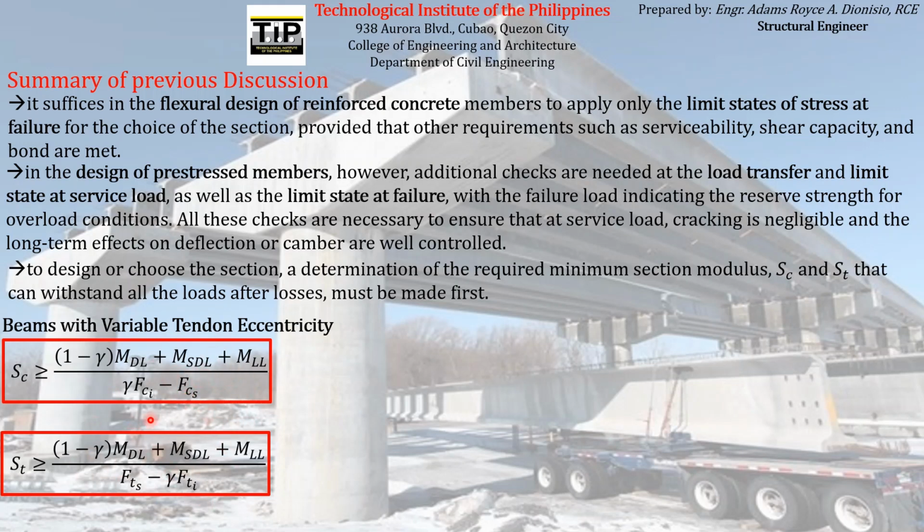And then we also derive a formula to find the maximum eccentricity so as to not exceed the maximum initial pre-stress that can be experienced by the pre-stressing reinforcement at service load condition. So we don't want that initial pre-stressing force to exceed that maximum initial pre-stressing force that we can compute on the design of the member at service load condition, because we don't want it to experience tensile stresses exceeding the maximum allowable tensile stresses specified by the code.